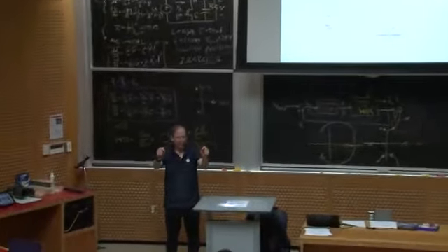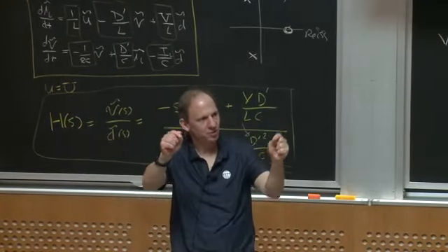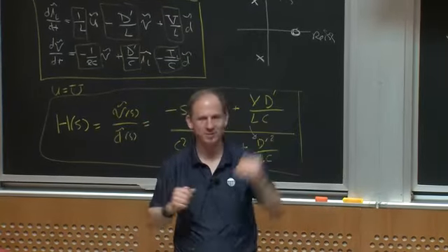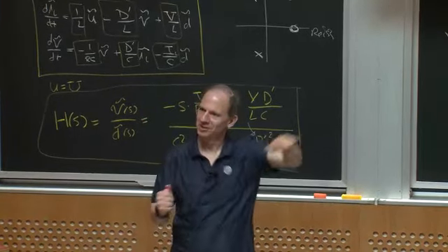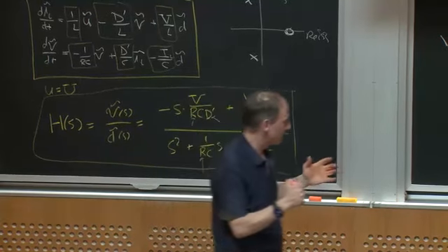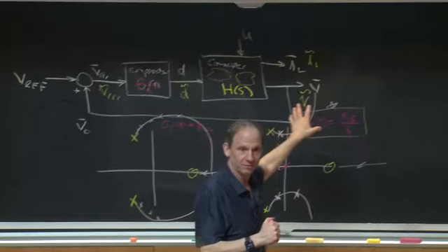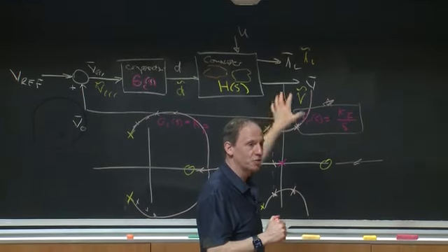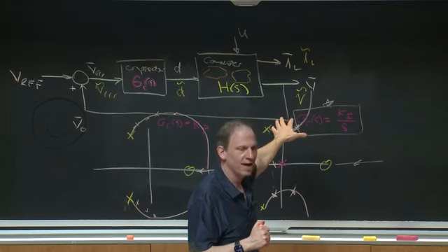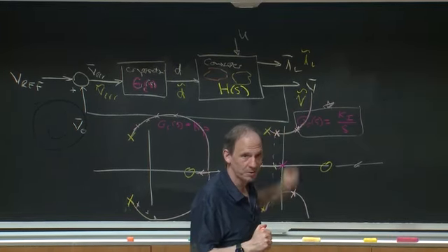So in addition to making your control loops stable, I would argue you've got to think about how precisely it has to track the output voltage. How much will it wiggle when something happens to it? And is that acceptable? In power supplies, very often your job is to make the world clean, solid voltage no matter what. And in those cases, you've got to think very carefully about how you want to deal with the closed loop poles, right? Maybe you want to make sure that no poles are super lightly damped, even if they're pretty far down and not contributing that much to stability. Maybe they'll make your output response unpleasant.